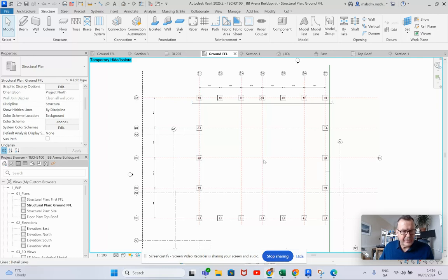Now we're ready to do the slab here of the hall area, and this is the way I'm going to do it. So I'm going to run a ground beam all the way around the outside, and that has two functions. One is that it'll stabilize the columns and the pads, and also provides a framework, if you like, to pour the slab in between.